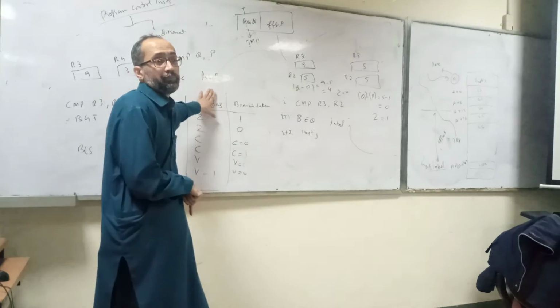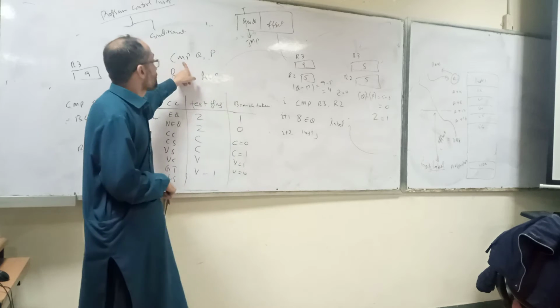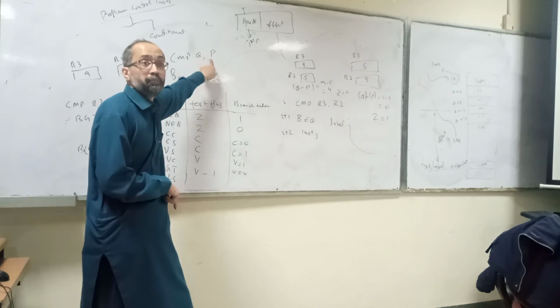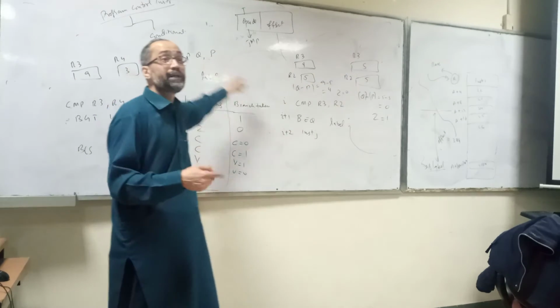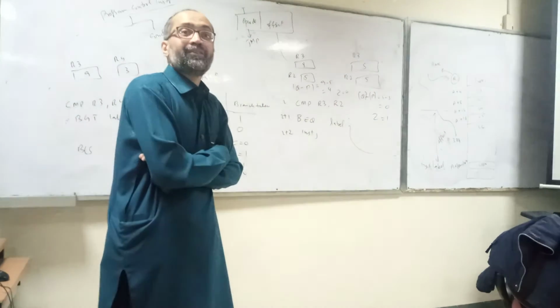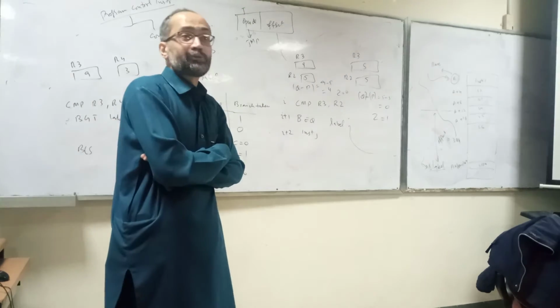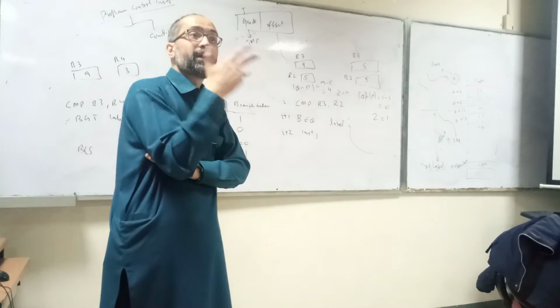But within the microprocessor, whenever you execute this instruction, compare Q and P, it will actually change the flags. And what are the flags? Which flags will be affected? N, Z, C, and V.